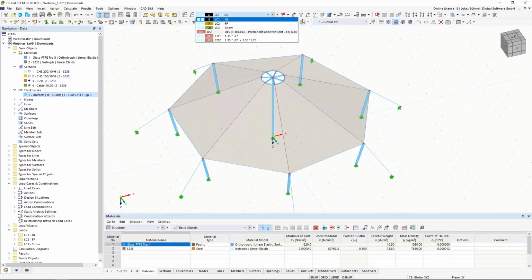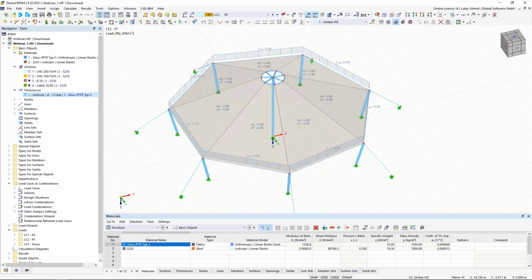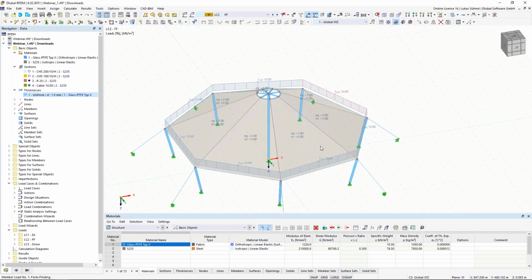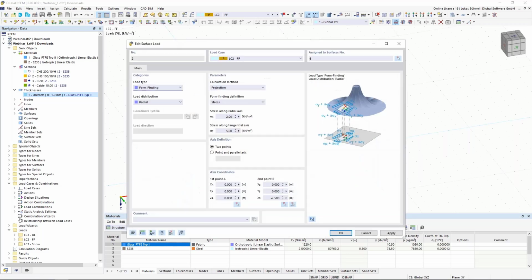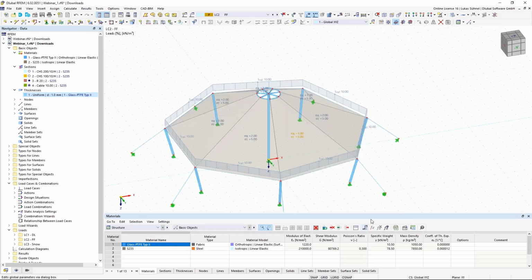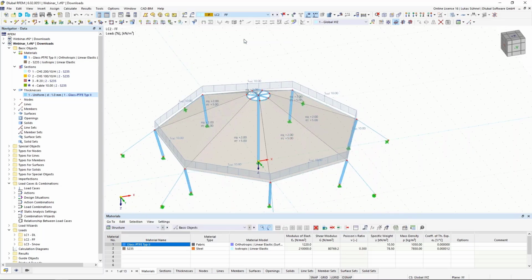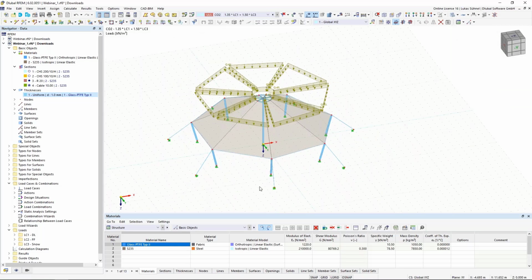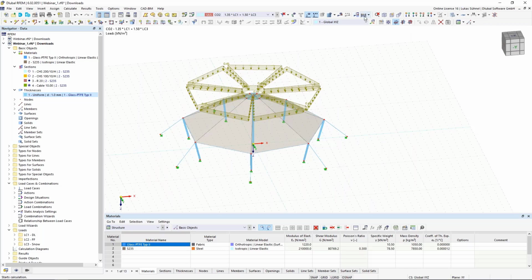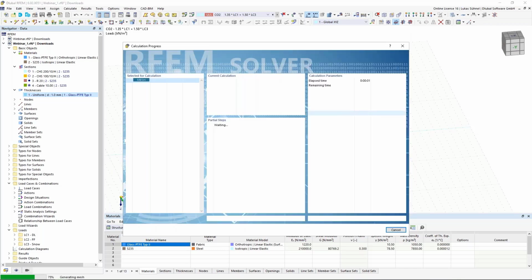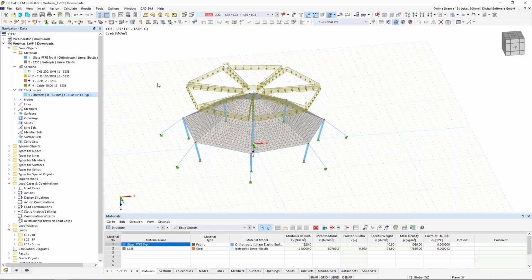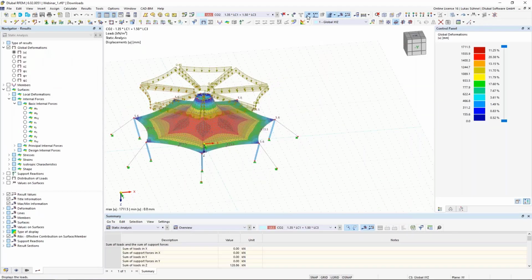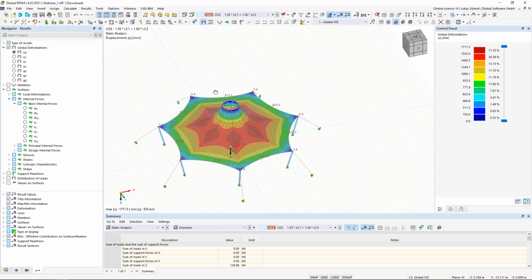And then I have all my load cases, my dead load case, form finding load case with the loads that I defined. Yeah, with the sag for my cables, and the radial pre-stress for my membrane, and also my combination. So anything that I defined has been exported, and I can calculate the structure now. The form finding load case, not the load case 1, not the load case 3, as you saw. I deselected them for the calculation, and then you get your results.